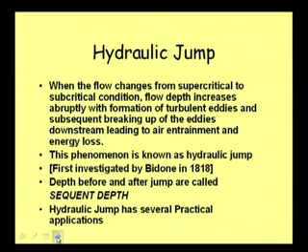Well, now with this introduction to hydraulic jump, let us try to define hydraulic jump. Well, when a hydraulic jump will occur, that is the first point. When the flow changes, you can refer to the slide, from supercritical to subcritical condition. This is a very, very important point to be noted, that the flow must change from supercritical condition to subcritical condition. At supercritical, the flow is coming with very high energy, and then due to some obstruction at downstream, or maybe due to the normal channel slope condition itself, the downstream depth is subcritical, then the flow changes from supercritical to subcritical abruptly and with a lot of turbulence.